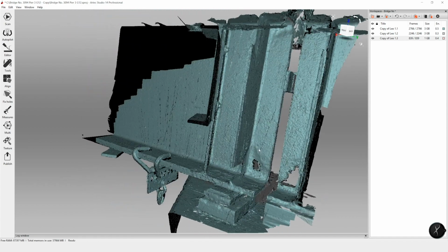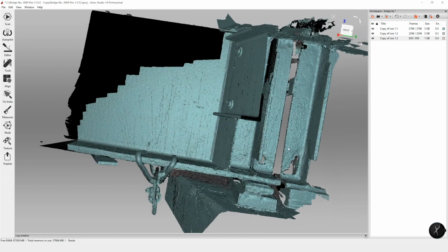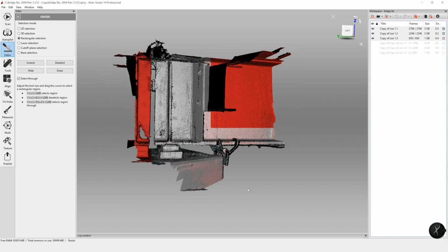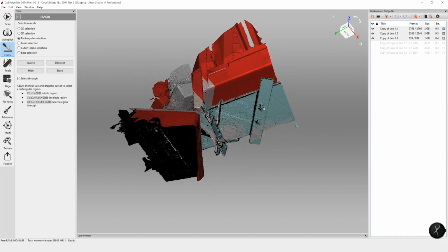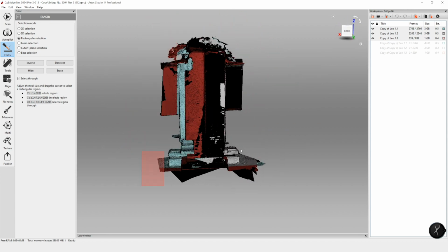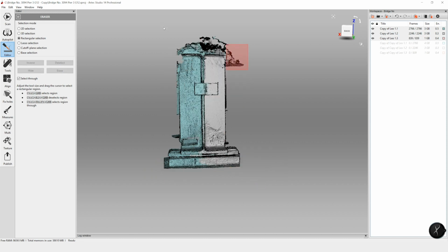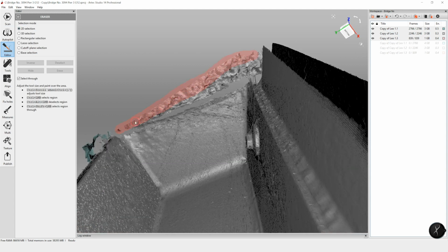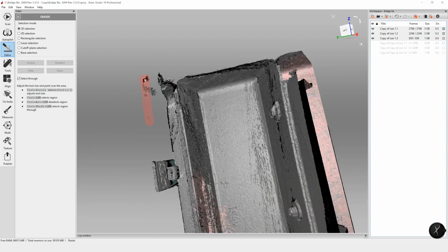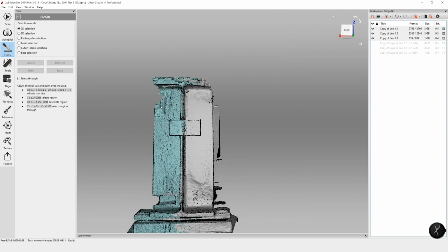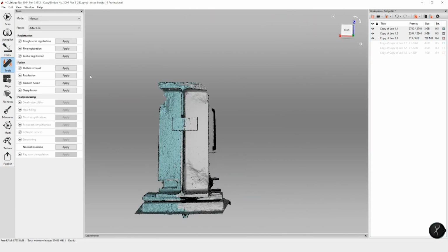First, as always, you want to go ahead and make copies of these scans now that they are well aligned. Once you make those copies, you want to go ahead and unload them so it's not taking up room, and then trim your scan. So we're only working with the beam information we're most interested in. And we can focus on any different area here. It's often nice if we want to do a first run where we erase information, but then you want to hold off and say, I can erase more after fusion. But whatever you're really interested in for that final product, make sure that you do that in your first round before you fuse. Once we've deleted all the extra parts of the scan, we can move on to fusion.